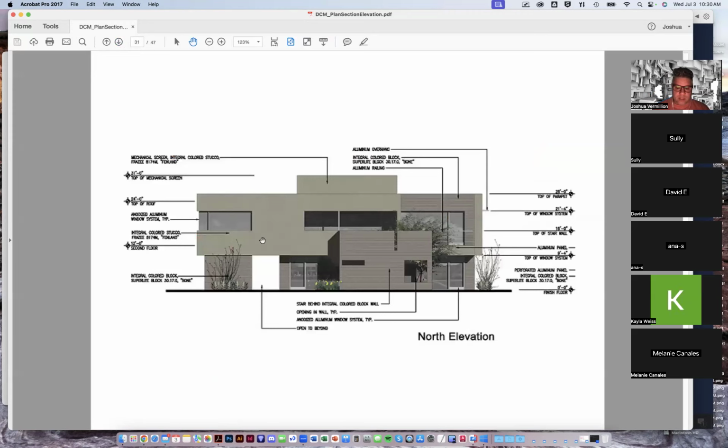Here's another example of an elevation. I'm not fond of how they put these leaders on here. Typically in a drawing at school, we wouldn't add all of these elevation markers and leaders. But certainly in a construction document set, you definitely have some tags here and there, as well as all the key elevation markers, to talk about the different materials and finishes, or you might have a bubble here to take you to another elevation to show things in detail.